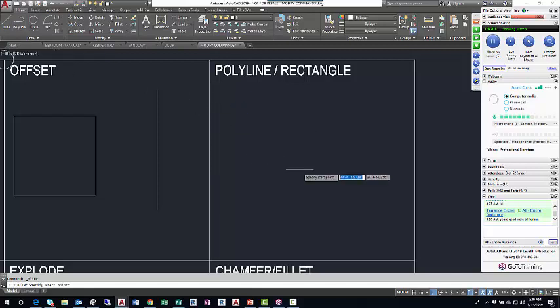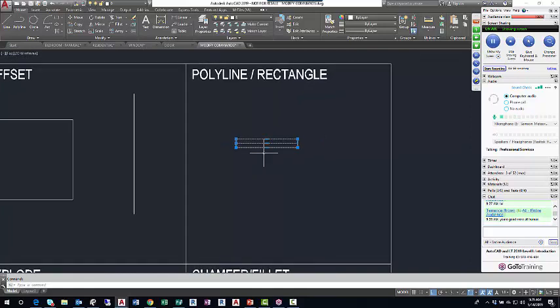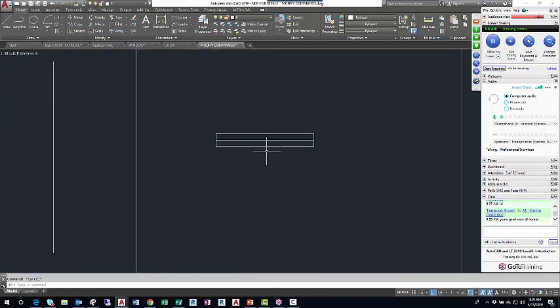I'll click Polyline, and like I said, I'll recreate that window that I drew earlier. Left click my start point, pointing up the screen, and then I'm typing in my distance, 2.5, enter. Right on the screen, 36, enter. Down the screen, 5, enter. Left on the screen, 36, enter. Up the screen, 2.5, enter. And then right one last time, 36, enter. When I'm done, I'll hit escape to cancel. What that's created is a continuous linear loop that crosses itself once, nearly.